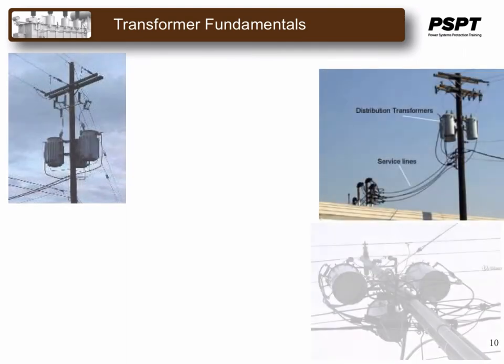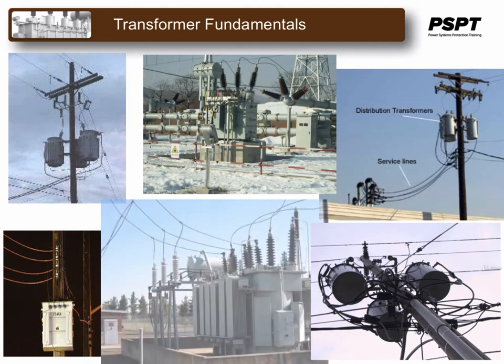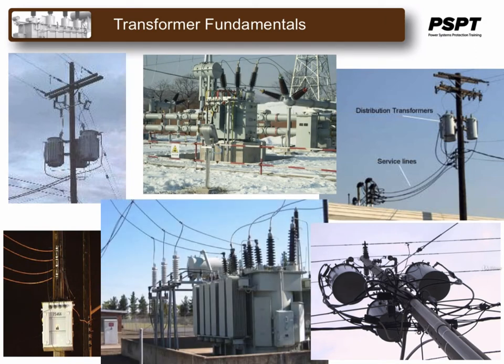Transformer and distribution stations, with very few exceptions, handle three-phase power, and the transformers are either three-phase units or three single-phase units in a bank. The exception to this is where two transformers are operated in open delta to supply three-phase power. This is not a common situation and is usually used in emergency situations. However, it does exist.